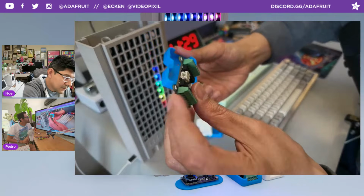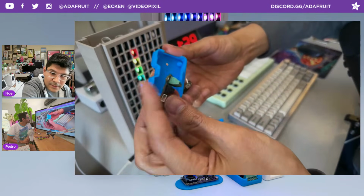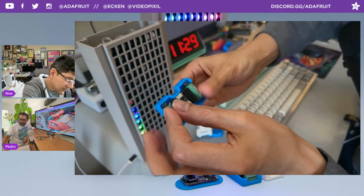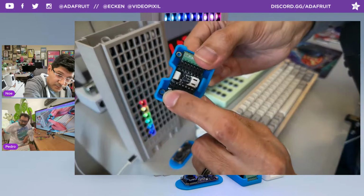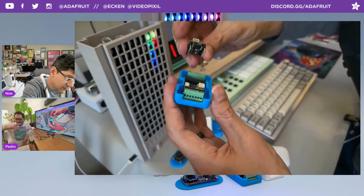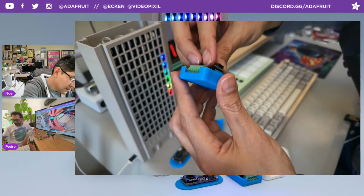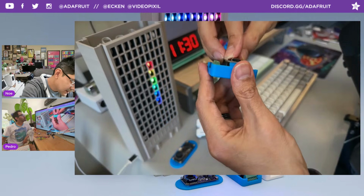And the way it fits is you just gotta line up the Stemma QT port with the Stemma QT port hole. You just fit that in there. There's these pegs that fit through the mounting holes there, so that it doesn't move a lot. And then your QT Py goes this way. Let's see if I can fit it in there. I have to look at it.